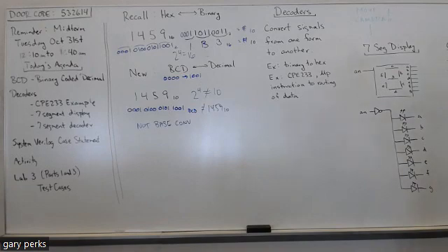I think I mentioned earlier that most of your data in this microprocessor is 32 bits. That's why you see a /32 on almost every line. So each instruction to this microprocessor is 32 bits long. So 6 to 0, that's identifying 7 bits of the instruction, bits 6 through 0. And then 14 to 12, that's 3 bits of the instruction. And then bit 30, that's a single bit of the instruction. So some of the inputs going into that decoder are bits of the instruction.